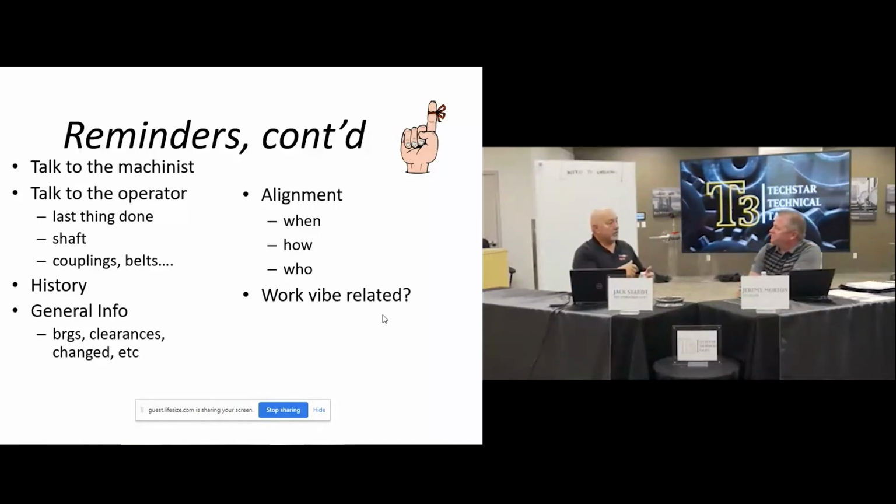Yeah. So I go back and I do my Columbo detective work to try to analyze root cause, what caused all this. Talked to the millwrights. The millwrights told me we didn't align it. And this is a turbine wheel that turns 5,400 RPM. And it's like, why didn't you align it? They said we didn't have to. And I go, why is that? And this was in October. They said, we check alignment every April, and it was perfect in April. And I was asking him, well, you broke the coupling, you pulled the rotor out. He says, yeah, but we never moved the feet of the case.